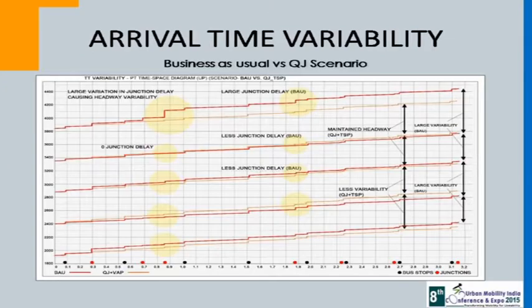Then we have the travel time variability of the various vehicles for the time we have run the simulation. We can see the variation of minus 88 seconds to 158 seconds. That is huge. That is plus minus 30% of the variation from the scheduled timing. Whereas in case of queue jumper and vehicle actuated priority, the variation is quite less, 0.5 to plus 10 variation. That is just 19 to 28 seconds.